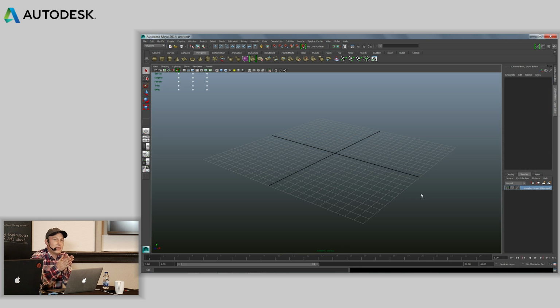Render passes happen at the shader language level. This is something that Mental Ray has the ability to do. During the render process, it will basically render a primary buffer, and inside of that primary buffer, it has the ability to extract all the different lighting components. So specular, diffuse, and utility things like vectors can all be extracted at render time and output to different files. So at the end of the day, they're both doing segmentation of your files to make multiple images. It's just that one happens at the object level and one happens at the shader level.